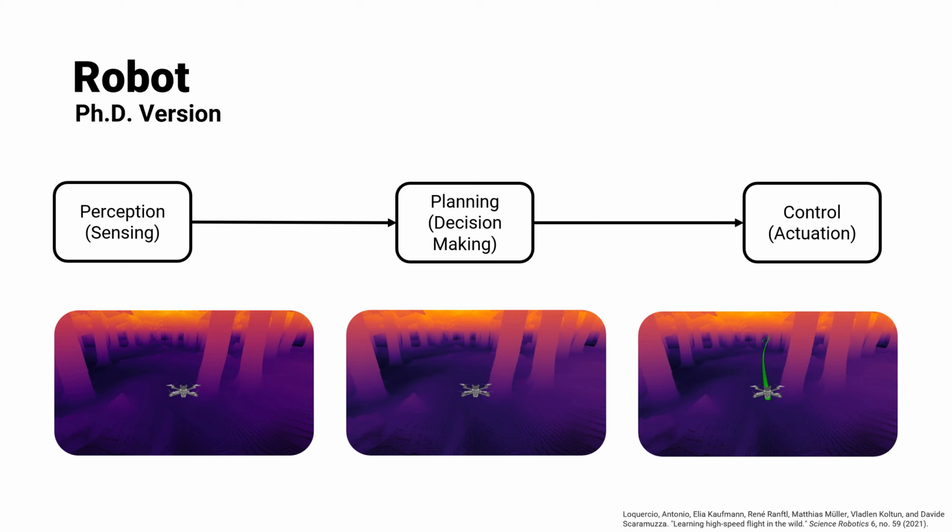And then for the planning side, you can have the input of this depth map going into the planning neural network, and the neural network basically spits out a set of locations, which is your plan of action, depending on what you want to do. And for the control side, generally there's a common term called reinforcement learning, which is basically used to know, hey, how do I change the motor speeds in an intuitive manner for the task accomplishment rather than a pure physical set of equations or math. And it's generally very useful for really complicated systems which cannot be mathematically modeled, right?